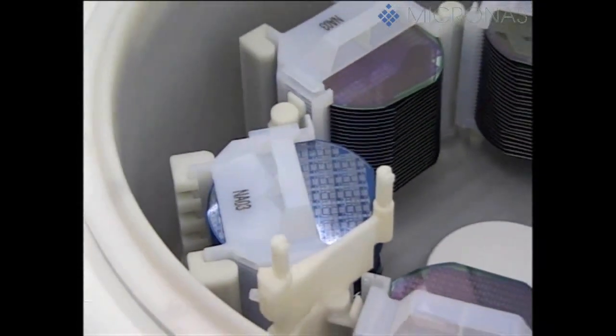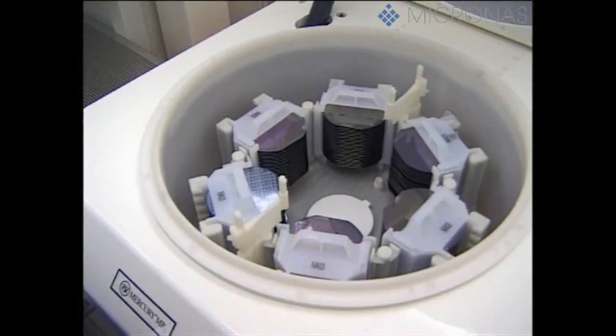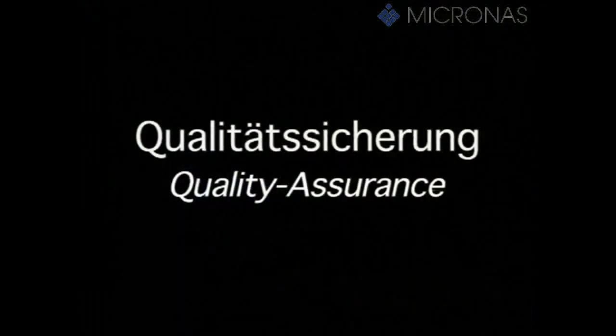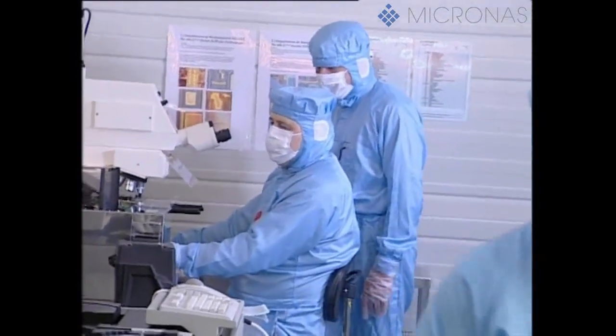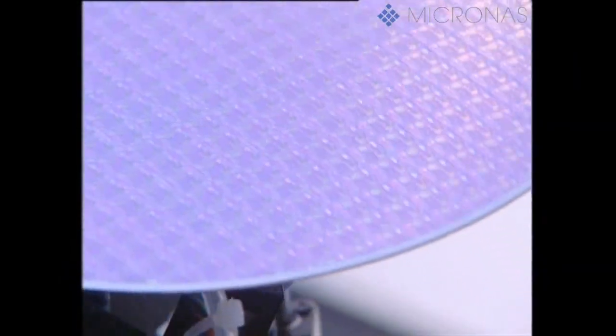Once implantation and etching have been completed, any photoresist that's no longer required is removed by wet chemical processes. Once the structures of all the photomasks have been transferred to the wafer and the required electrical properties achieved in all the layers of the integrated circuit through the processes described, the production steps in Wafer FAB are now complete.